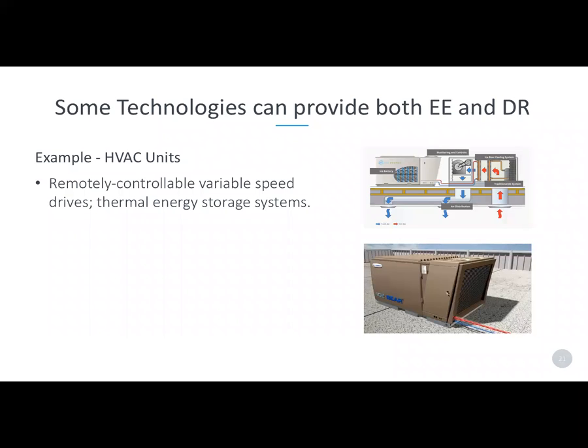And so you're able to create ice at times when, again, it's less of an impact on your utility bill, and also it's more efficient to do so. Then in the middle of the day, as temperatures rise, when typically air conditioners would start turning on and providing cooling when the price of electricity is higher and when it's less efficient to provide cooling, these technologies pull heat from the building, melt the ice, and then that cools the air. They're able to provide air conditioning with essentially no energy usage during those times.